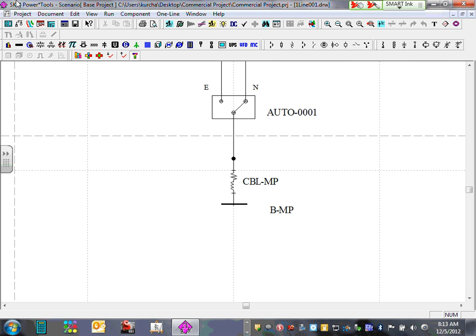Minimize that. So I'm going to go cable. Now, because I have 2 panels coming from the same bus, here's what I do. I click on this bus and hover over the edge, the end. When you hover over the end, do you guys see these 2 arrows? Can you guys see that? When you see them, hold right, hold left, and drag. So you can extend your bus from the right and the left. Your bus becomes big, fat, and fluffy.